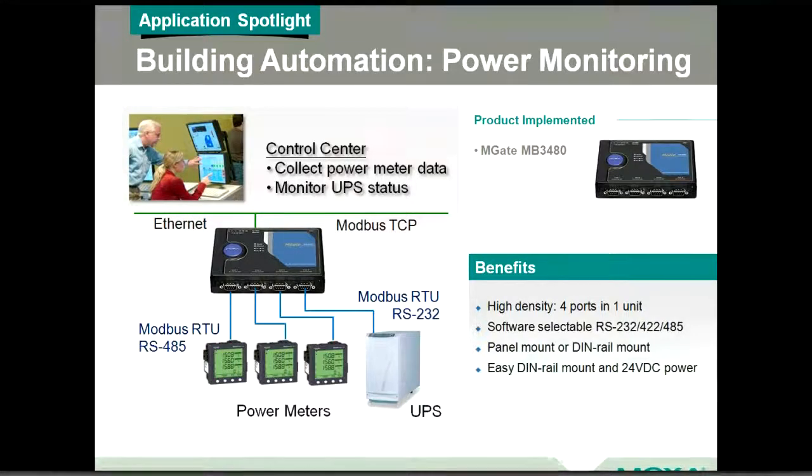And even today, and I'm using the example of a formerly Square D here in North America, known now as Schneider Electric power meter, these are new devices. They don't have an Ethernet port, and you can only get at them with a serial connection. So if you want to get at these more than a couple thousand feet using RS-485, you need to have some way with which to do that. Here's a great solution by being able to tie that together and bring in those assets from your sub-metering within your panels, back into a control center where you can go ahead and monitor what's happening.